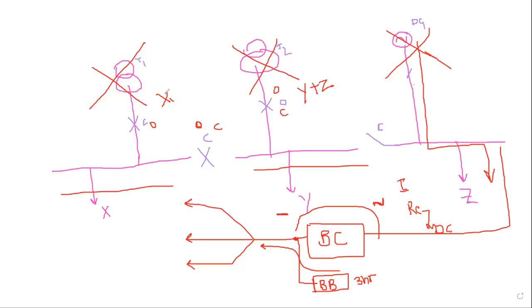If both transformers have failed, you manually open this one switch and close this. So the DG generator will feed only the Z loads, which include the battery loads. If this cable or battery charger failed or the DG set failed, then the battery bank will feed these loads. So this is the entire simple scheme for our AC and DC distribution.